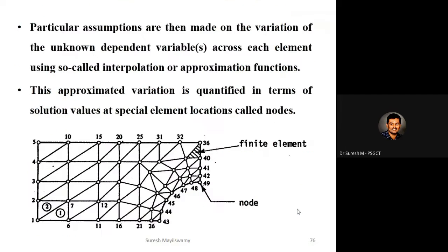And so in this diagram, this triangular part is called an element and these dots at the edges are called nodes. So here the forces are not concentrated, only here there is a hole, so that the maximum force is concentrated on this area. So I can divide these elements into small parts so that the analysis will be more effective in this area.